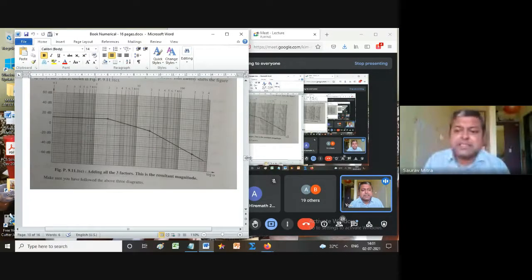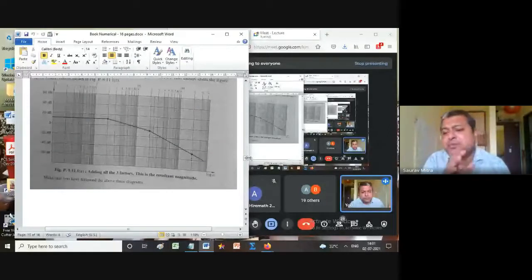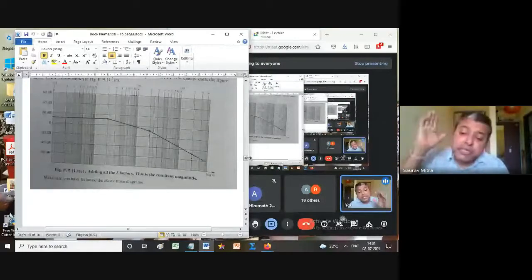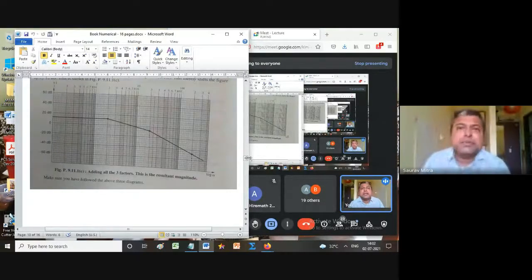Second thing, just I will tell this statement and I'll conclude. After phase plot, you have to draw the phase plot the way you have found for 8 radian per second, the same way you have to find for 0.1, 1, 10, 100, 1000, 10,000. Okay, and you will be finding that at 10,000, it will be very close to minus 180, but it will not touch minus 180. It will touch minus 180 at omega equal to infinity. Last line you can write down that omega PC does not exist. That means phase crossover frequency does not exist.